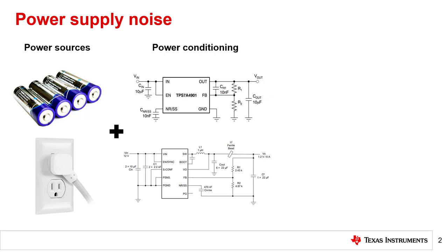The supply source, as well as the active and passive conditioning components, contribute some level of noise, which manifests itself in the power supply output as a variation from the expected voltage. This variation could appear as a steady DC shift in the output or as an AC signal at some frequency and amplitude riding on top of the output.